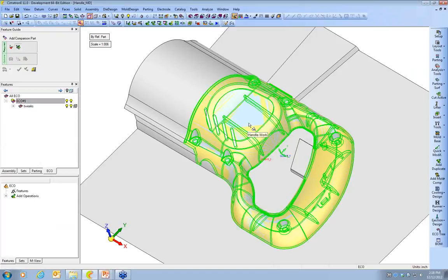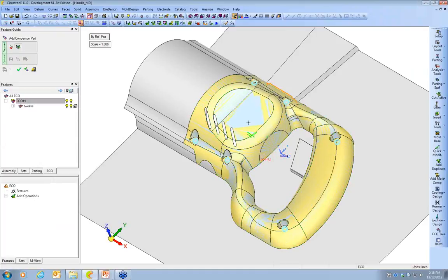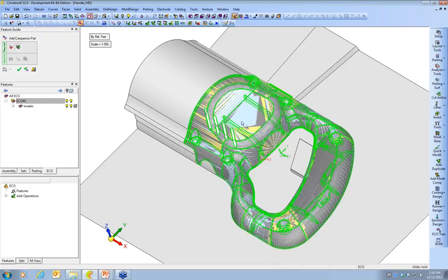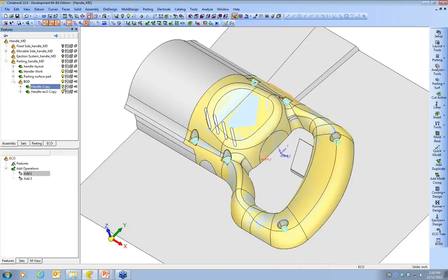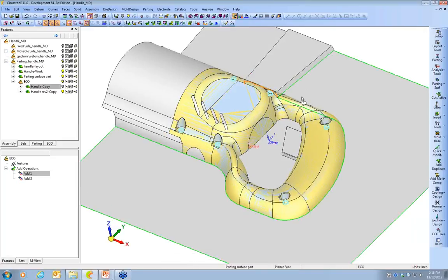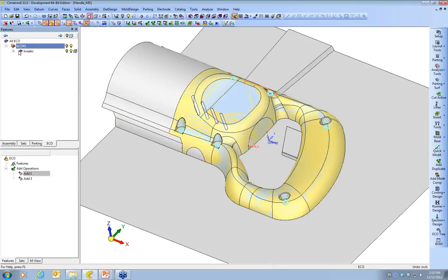So let's add this one into the assembly. And again, we'll just use the work part to supply the location and the plastic shrink value for it. So in this first example, this first change, what I want to talk about is that top-down approach for bringing the new data in right at the very top step of the design. Because of that, when I do the comparison here, I'm just going to use the old and new customer data files. Nothing about the existing mold design yet.